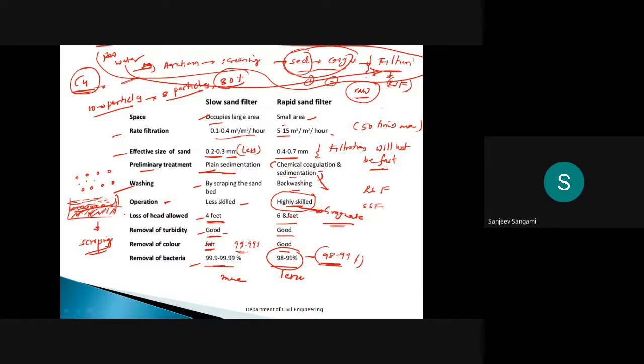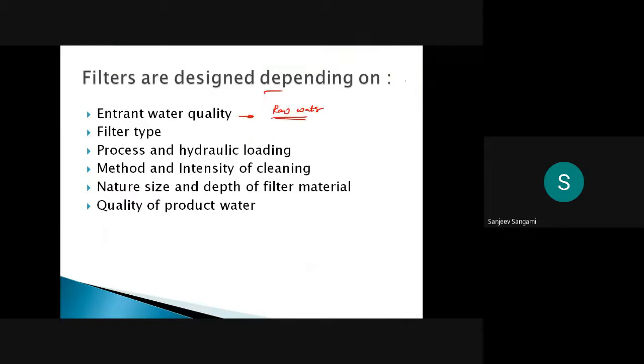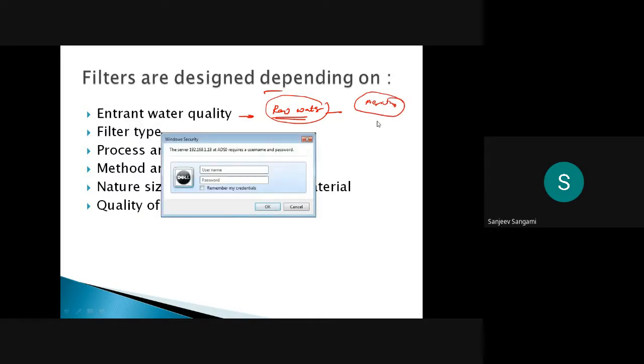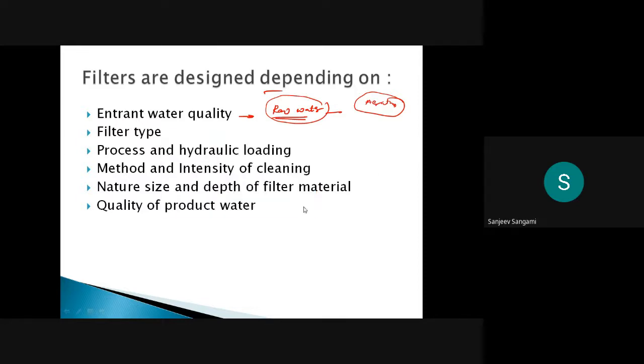Okay, so raw water, aeration, screening, sedimentation, coagulation, filtration. These are the kinds of units we are providing in most water treatment plants. Suppose you are deciding on aeration or screening. On what basis have you decided whether aeration is required, whether screening is required, whether sedimentation is required? On what basis are you going to design it? Ultimately it depends on the raw water quality, remember.